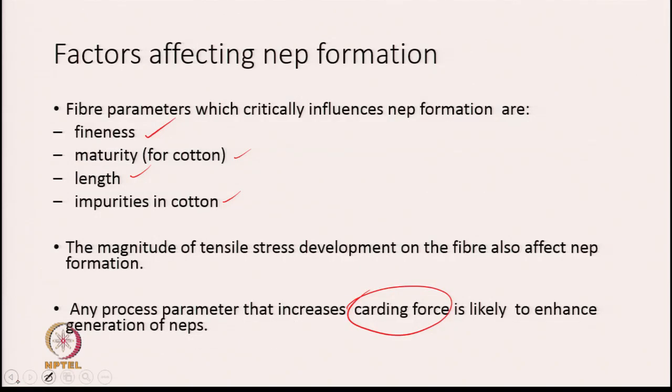So, this stress level during carding, especially the level of stress which acts on the fibers between flat and cylinder, is very important. So, there what matters is the space between flat and cylinder. If the fibers are long, there will be a lot of force development on them, because there will be a lot of